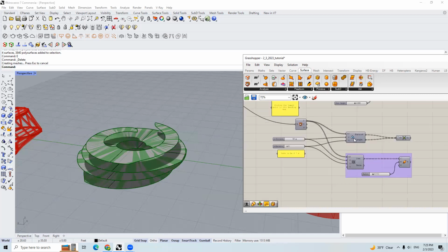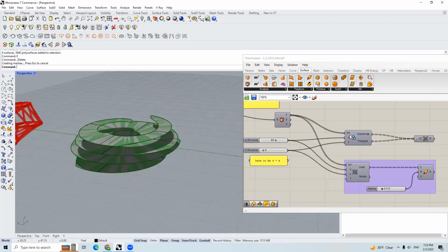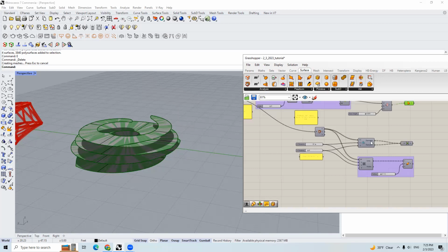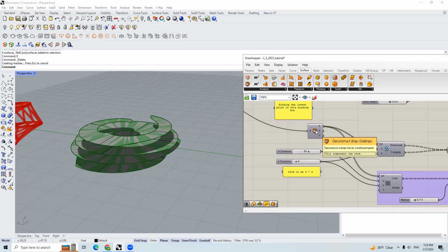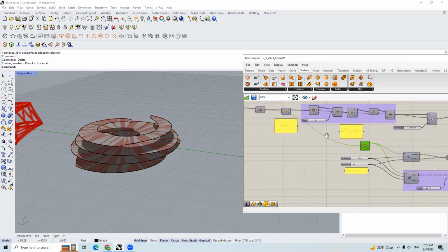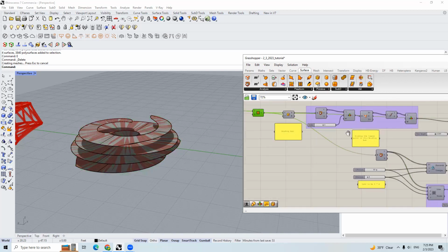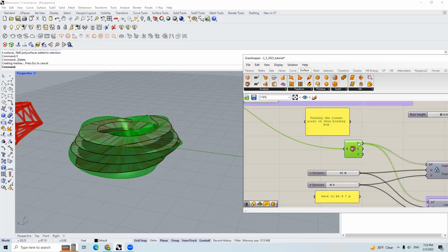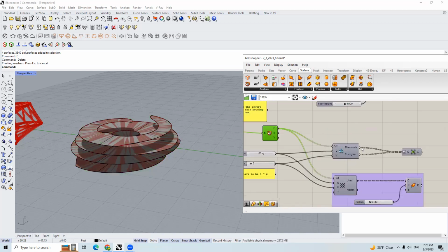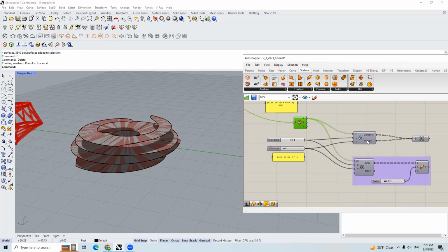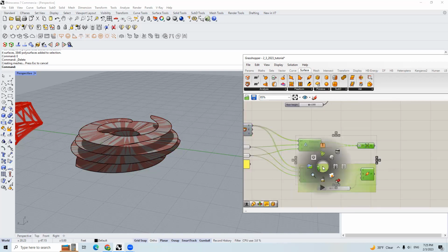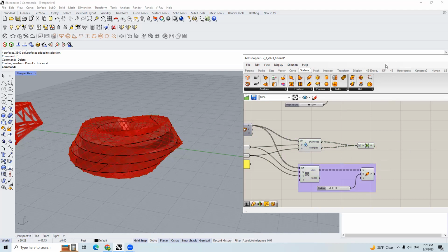And then I will generate those surfaces based on the exploded surface. This constructs this wrap, which is this polysurface here, and we explode it, making it into 4 different pieces. And then we will generate those surfaces based on those pieces with the help of Lunchbox.